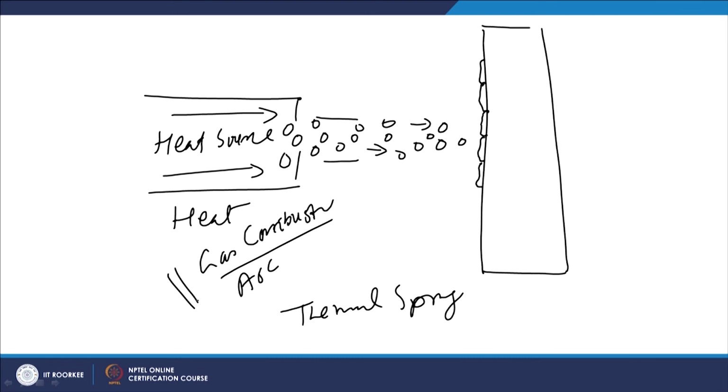of the coatings, the cooling rate experienced by the metal which is solidifying, is very crucial as far as the performance of the modified surface layers is concerned. So, in thermal spraying, after the solidification we get the layer of the required material, but here the substrate is in the solid state, and molten or semi-molten particles impinge on the substrate, and after flattening they solidify.